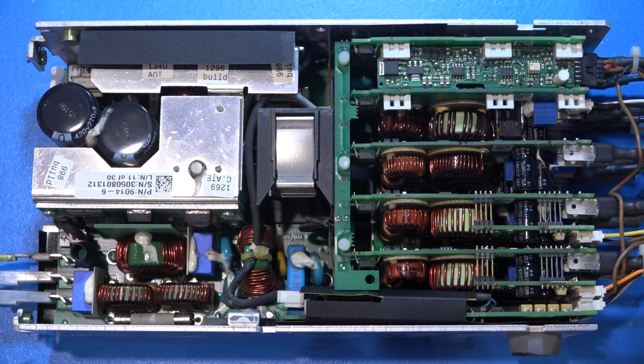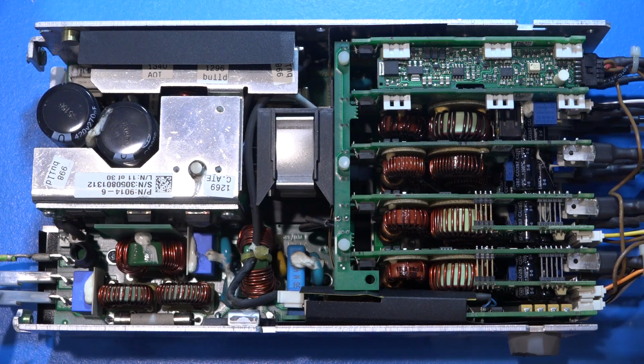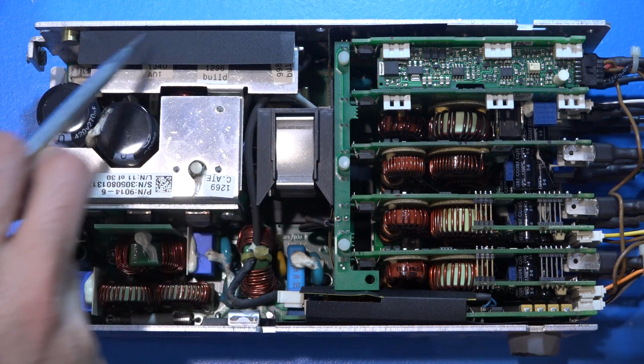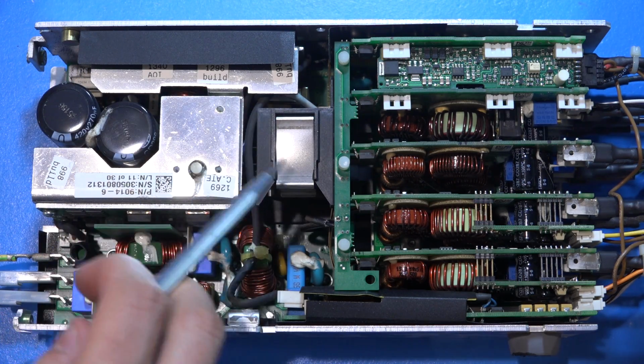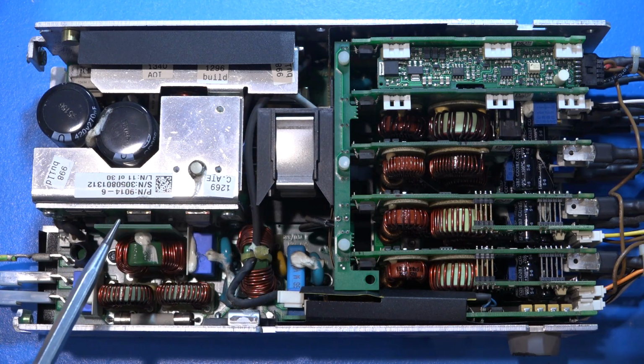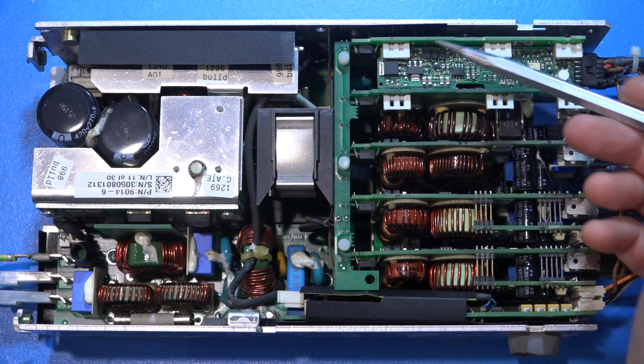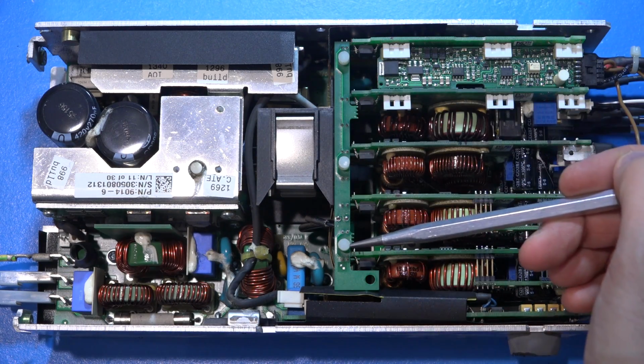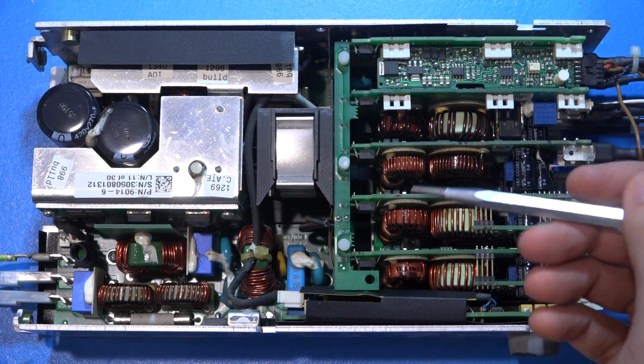And here is the inside of the power supply. And as expected, it is compact with a lot of different PCBs vertical, horizontally mounted. They're trying to save as much space as possible. So the input line comes over here. You can see the input filtering. This is the main part of the power supply where you have the rectifier voltages being stored here with a DC-DC converter portion here. And then some voltages are generated, passed onto this bank. And these banks are actually connected with a ribbon cable, which you cannot see, which is quite interesting in itself.